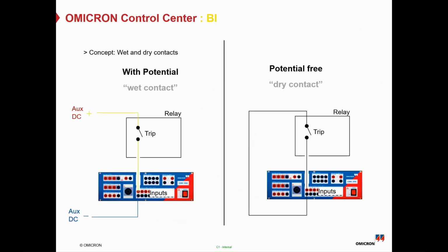But if you are using a potential free or dry contact, which means a spare or voltage-free contact, make sure also to configure the right configuration in the Test Universe to get the right feedback.